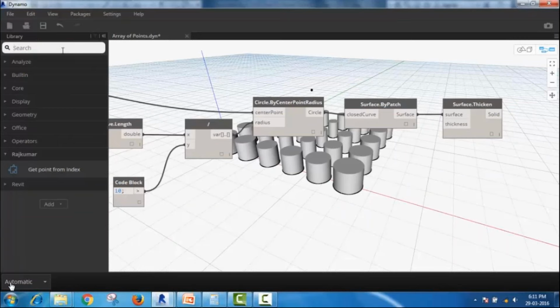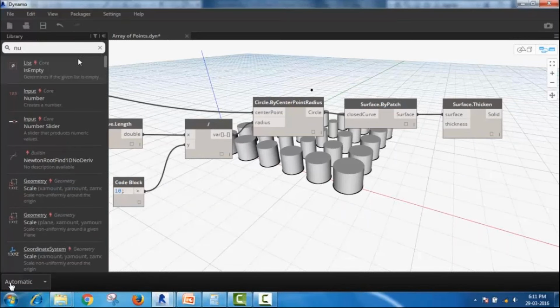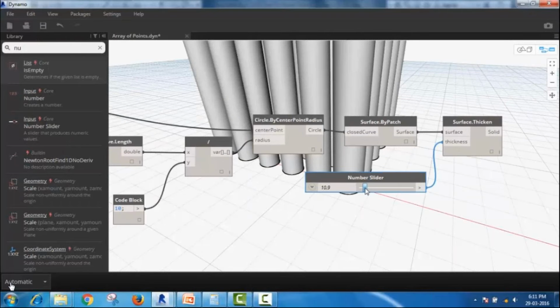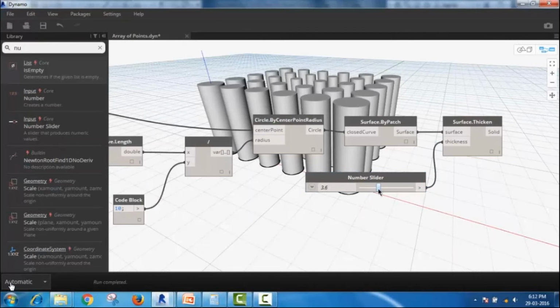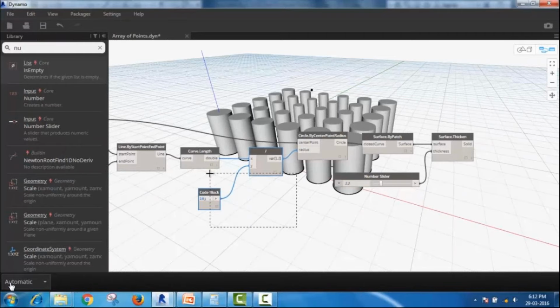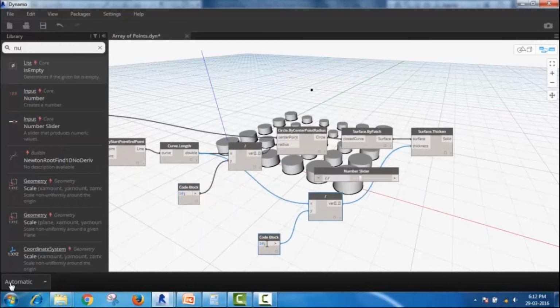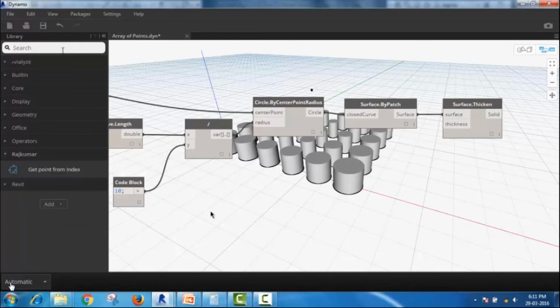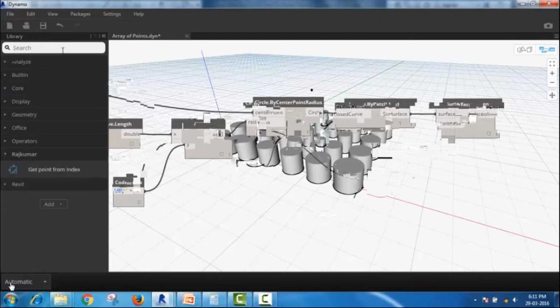And the same logic, the number node, you can adjust the height of the cylinder. It's so big, so you can control the value with a minimum and maximum value, or otherwise you can apply the logic as before. You can apply a divided value. Depending on multiplication, you will be able to control the height of the element.